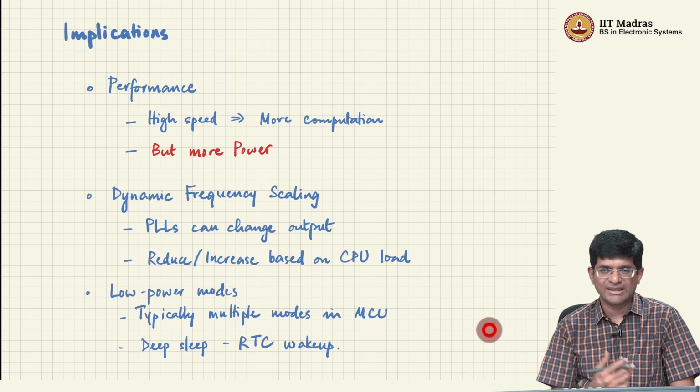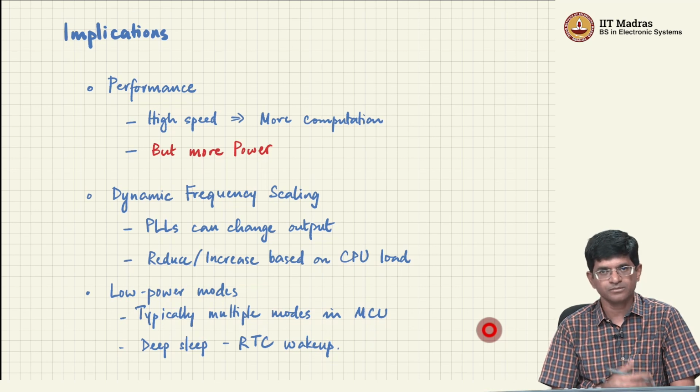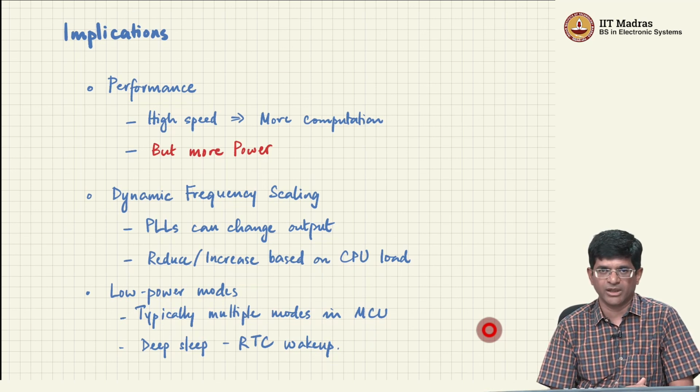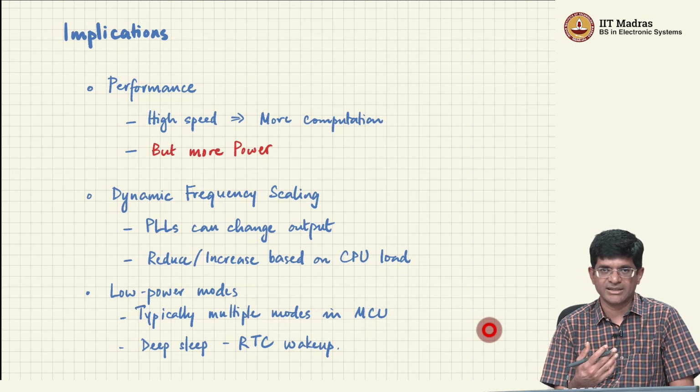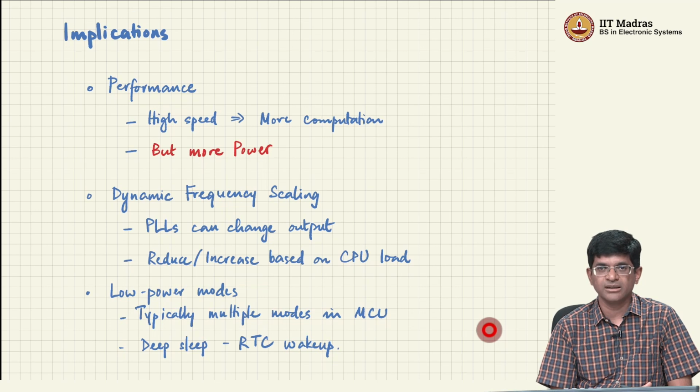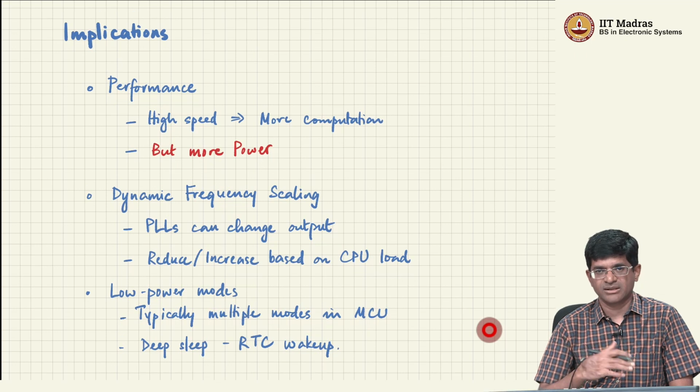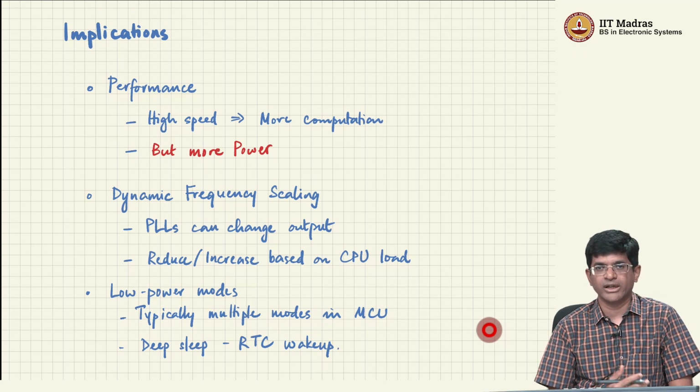And why that is happening is that your CPU has basically responded to the fact that it has more load, more work to perform, kicked up the frequency at which it's operating, which means that it is more responsive. As far as you are concerned, you see it as, hey, I'm able to play a game smoothly, but the flip side is it's heating up, more power is being dissipated. Okay, so this can happen dynamically. Most computers today actually have mechanisms by which the software can control at what point to switch between different modes of operation.